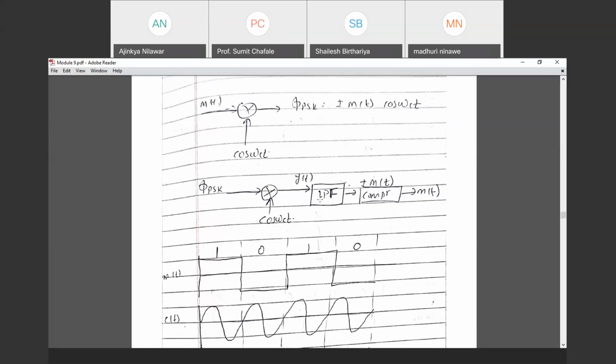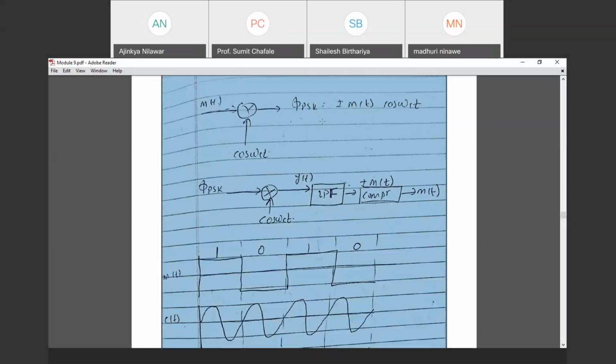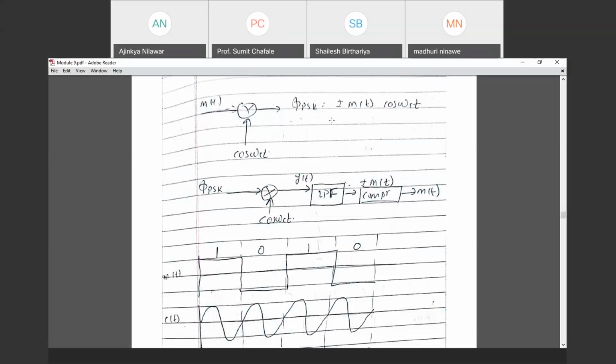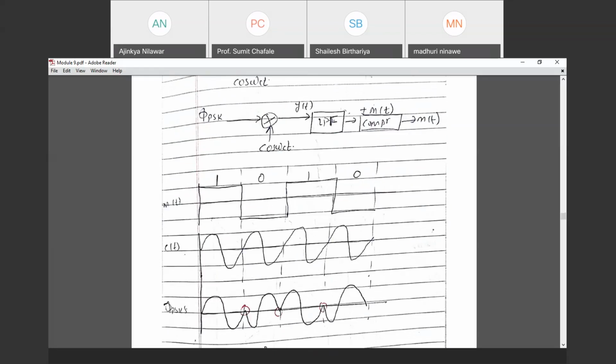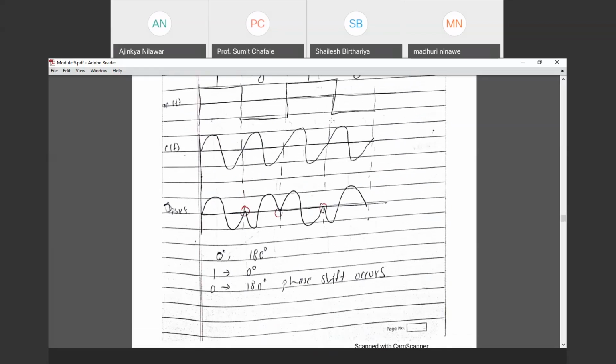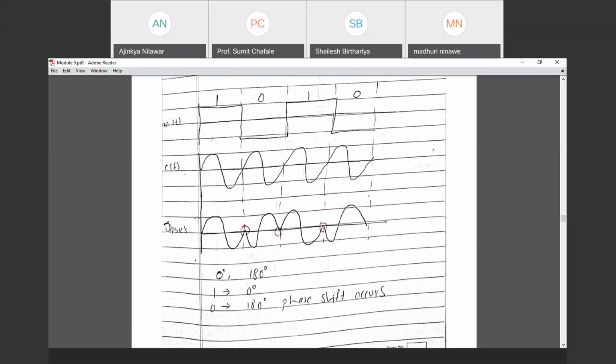Okay. So the next point is dealing with this, particularly the PSK technique, right? So we are having an input signal and then this PSK signal; how is it generated? Before moving to how these signals are generated, I just want to say something. Since it is binary, the entire phase shift we consider as 360-degree. So 360-degree divided by 2 is 180-degree.